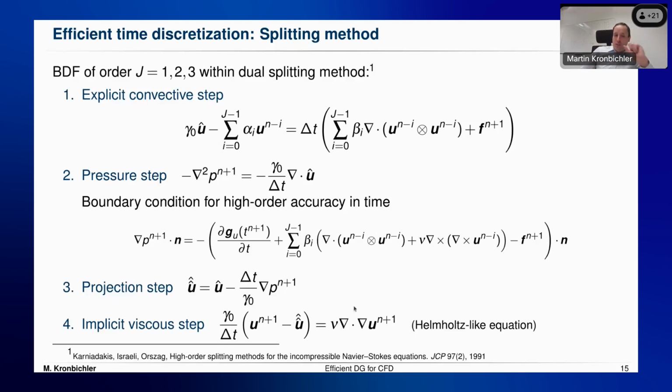But actually, I think this is the nice thing about this velocity correction that you see here: it is not as bad as the pressure correction methods, which are more common, because in pressure correction you really have to decide if you want to have inconsistent boundary conditions or divergence-free errors. Whereas in this case, the third step actually does impose the boundary condition, but it also preserves the divergence-free condition, if I remember correctly. But I could look into it more precisely, or we could discuss at some other occasion. Yes. Okay, thank you. You're welcome.